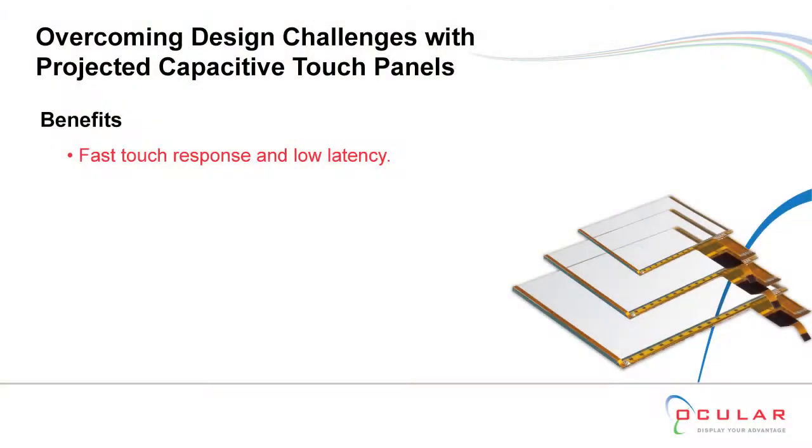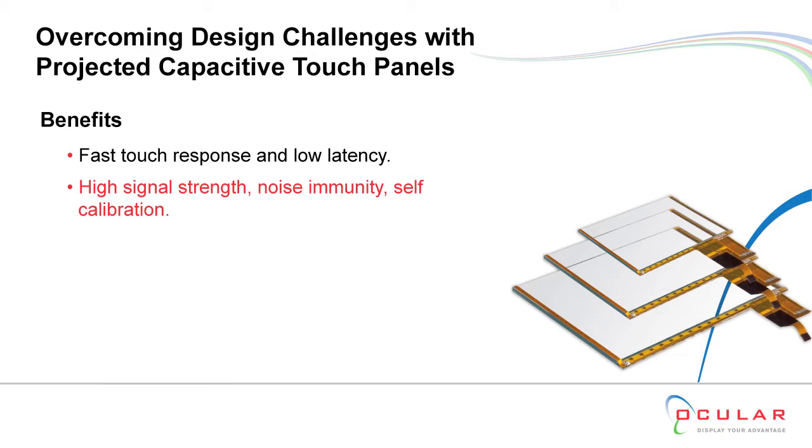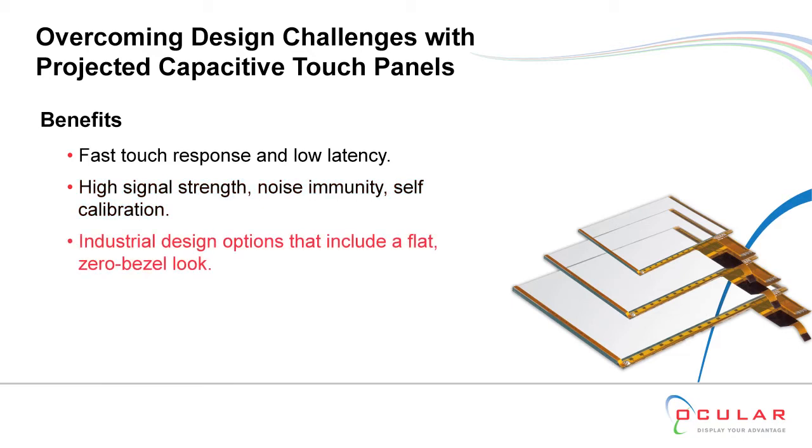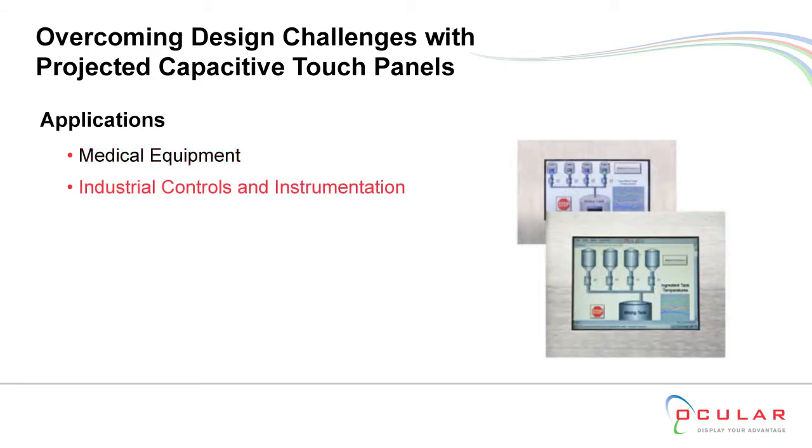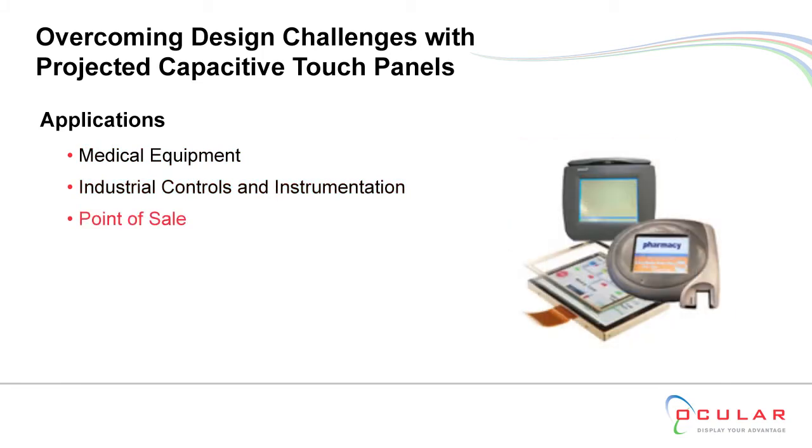Projective capacitive, you have fast touch response, low latency, high signal strength and noise immunity, self-calibrating, there's a lot of features. Works in a variety of applications, bare fingers, gloves, stylus. Medical application. You have industrial control and instrumentation. There's, again, a lot of these you've seen already.